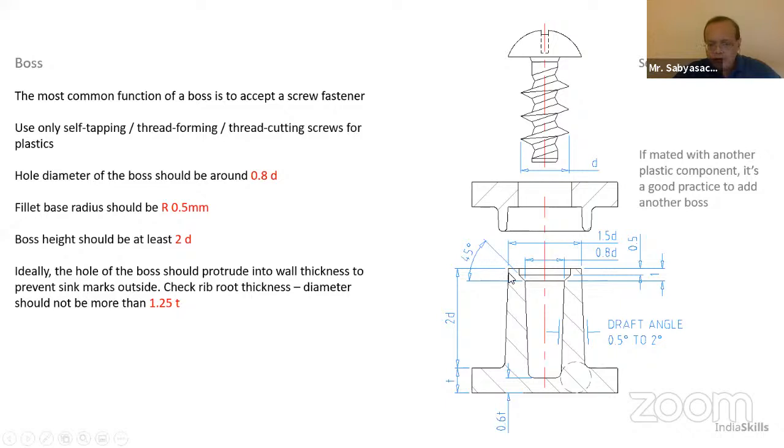If you don't give this little wider space here, the material that is scraped up starts pushing against the component on the top. This little space allows the cut material to rest there, and it never pushes the component up.